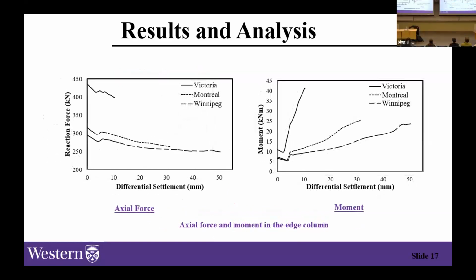So again, as you can see over here, the reaction forces are decreasing in the column 2 bays away. However, the moments are increasing. And again, even though they're increasing by different magnitudes, they're all experiencing the same trend.